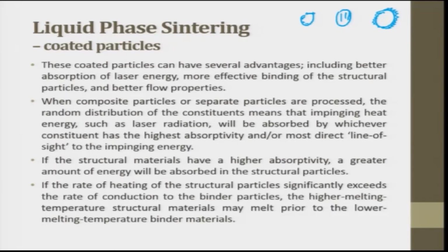These coated particles can have several advantages, including better absorption of laser energy, because this fellow can absorb. See, interestingly, laser has a property called absorptivity. This absorption property always depends on the material. It's a material dependent property.